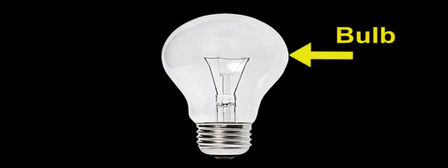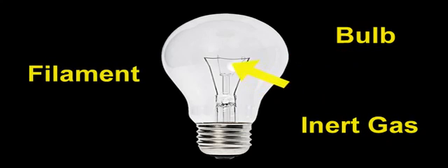Incandescent lamps are the oldest, least expensive, and least efficient electrical light sources. The glass envelope or bulb of an incandescent lamp gives its shape and contains the inert gas and the metallic filament. Other parts include the arbor, the stem, and the base, through which the electrical connection is made. A standard incandescent lamp produces light when the filament is heated to an extreme temperature by the flow of electricity. The metal gets so hot that it glows white, emitting visible light. The process is called incandescence.